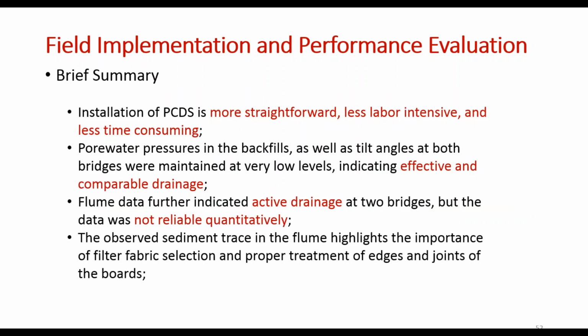So as a brief summary regarding the field implementation and performance, so the installation of the PCDS is actually more straightforward, less labor intensive, and less time consuming. And the pore pressures in the backfill as well as the tilt angles at both bridges were maintained at a very low level, indicating effective and comparable drainage.